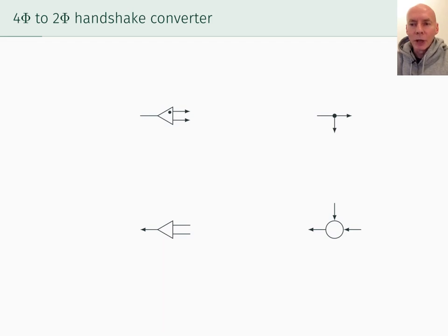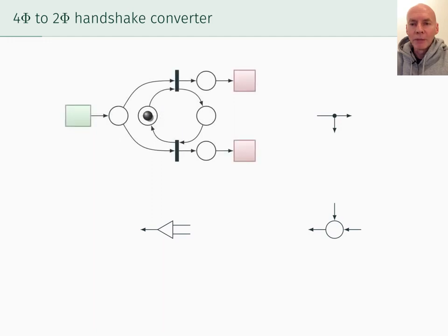So, for example, we could model a toggle with a Petri net like this, and the idea is that when the input terminal changes its level, this transition fires, which marks that place next to it, which enables this transition on the top to fire, which marks those two places, which makes this top output fire as the next observable thing that happens.